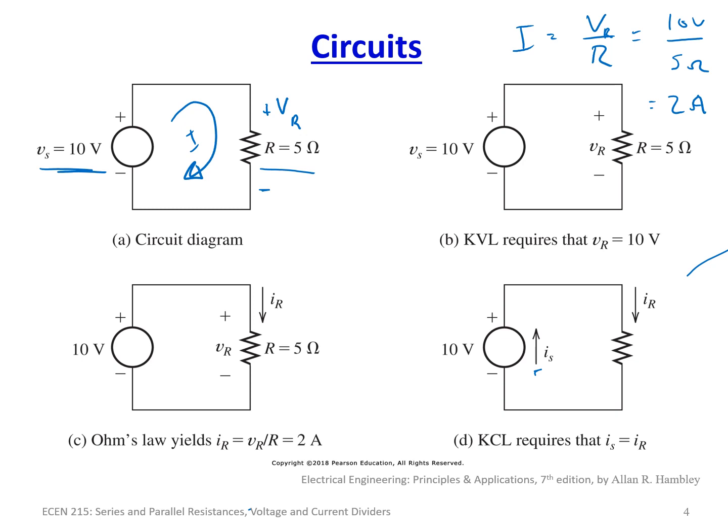Now, just to hammer home the concept we had the other day, we have two types of power going on here. We have generation power, or supplied power, and we have absorbing power. So let's ask this question. If I've got this power supply here and the current is leaving out of the positive terminal, going this way, and entering the negative terminal, then the current going through the resistor is entering on the positive and leaving on the negative.